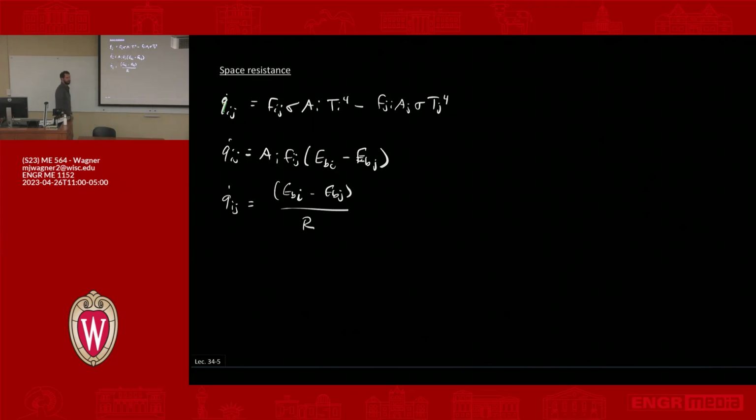So the units on this are a little different from typical resistances, which is why we call it a space resistance, or I will also call it a geometric resistance. And I'll call it geometric resistance because we're going to use the nomenclature R_g for this resistance because it has different units. The units on this resistance should be 1 over meter squared.